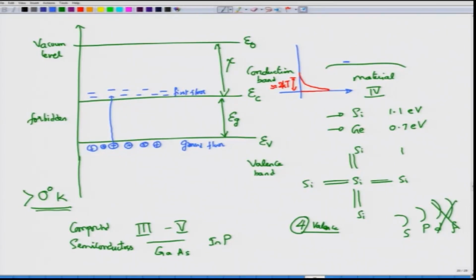And in a pure semiconductor material, for example silicon, the concentration of electrons is nicely balanced with the concentration of the holes. If you look at the concentration of the holes, it will again be quite large at the band edge, and then drops out with the width being typically about 2 kT. So, after 2 kT there are almost no free holes here, and about 2 kT from EC there are almost no electrons. So, this is just an example of electrons always hugging the bottom of the band, whereas holes are always floating to the top.